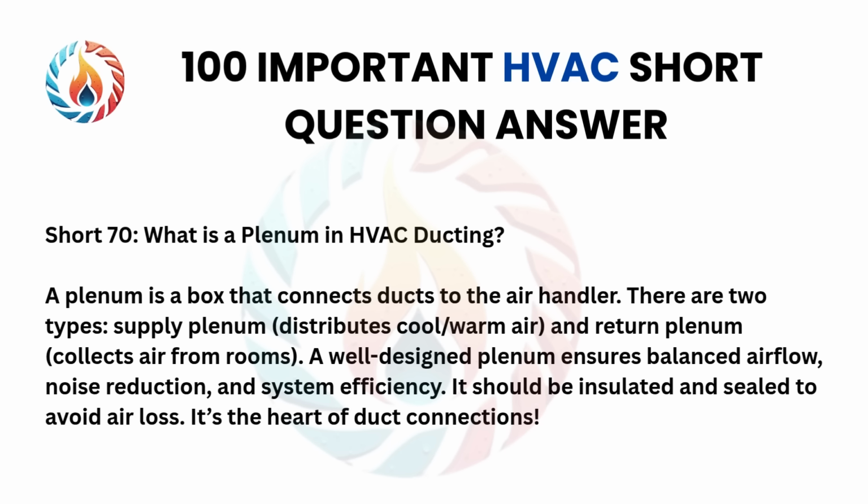Short 70. What is a plenum in HVAC ducting? A plenum is a box that connects ducts to the air handler. There are two types: supply plenum, which distributes cool or warm air, and return plenum, which collects air from rooms. A well-designed plenum ensures balanced airflow, noise reduction, and system efficiency. It should be insulated and sealed to avoid air loss. It's the heart of duct connections.